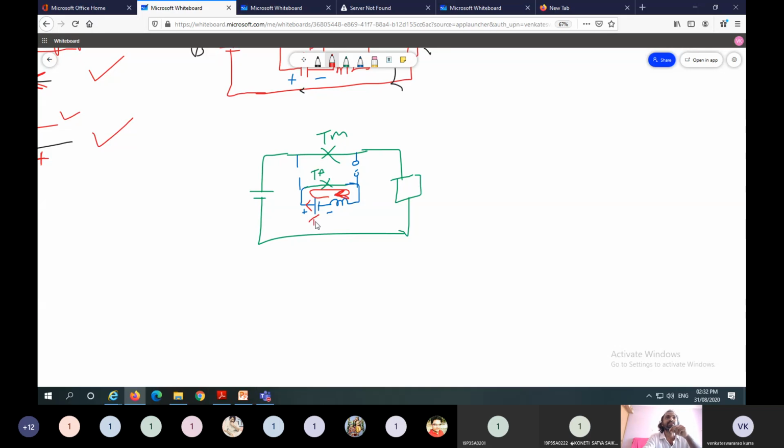So this one is the capacitor current, which is equal to the auxiliary thyristor current. So here both currents are the same. Here we already derived, for the LC resonance circuit, the formula for the capacitor current: IC equal to square root of C by L times (Vs minus Vc naught) sin omega t. So here the capacitor is isolated from the source. There is no connection with the source. So Vs equal to 0.